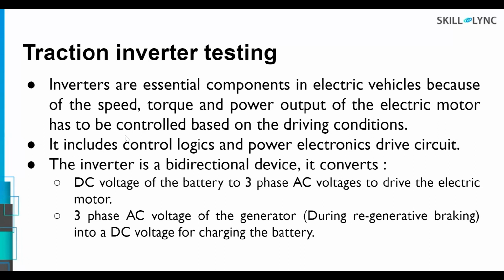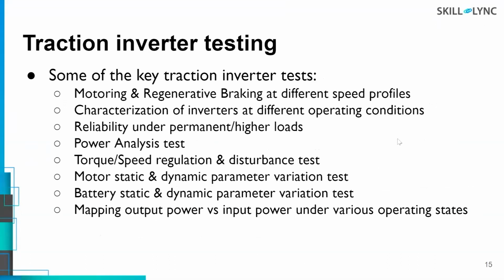That's why when it is coming to the traction inverter, definitely you need to have those kind of things. Okay, so that is something regarding the traction inverter. These are some key traction inverter tests that are going to happen: power line analysis test, torque and speed regulation test, motor static and dynamic. These are some scenarios where you need to ensure that your traction inverters work accordingly.